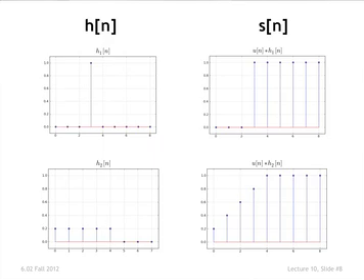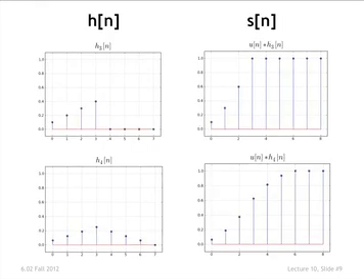And there are other examples on the slides. I won't go through all of them. I'm going a little slow here because we miss a recitation tomorrow. Recitations tomorrow are office hours, so I wanted to actually give you a few examples. Here's a case where the unit sample response increases linearly and then stops. And so the unit step response actually starts to accelerate quadratically and then stops. Okay, this is the discrete time version of integration that we're looking at.